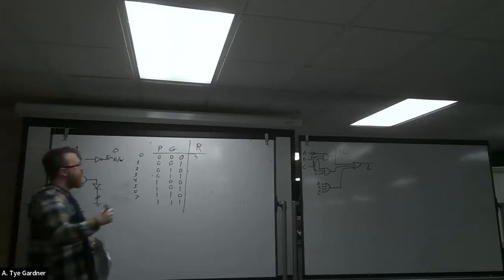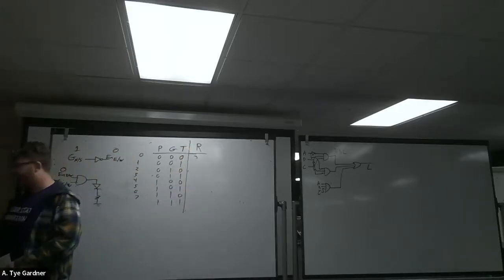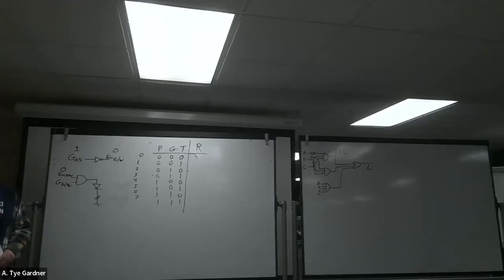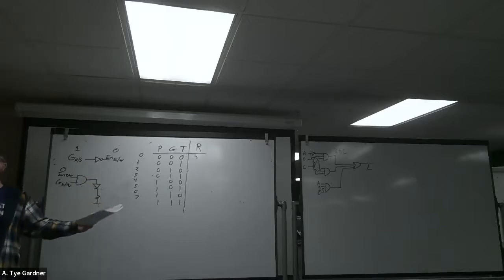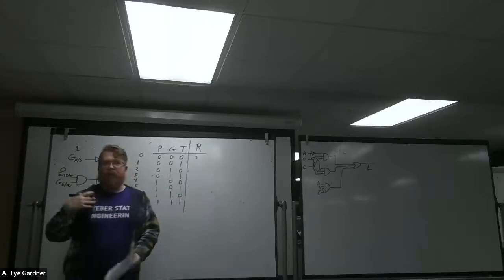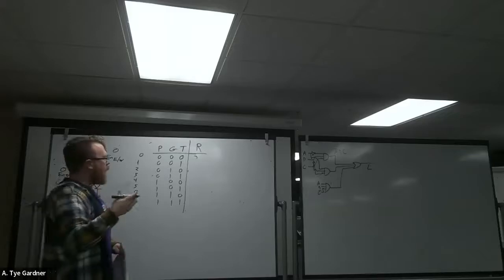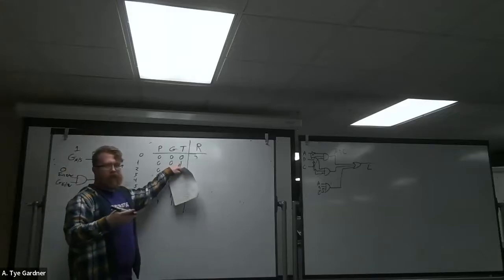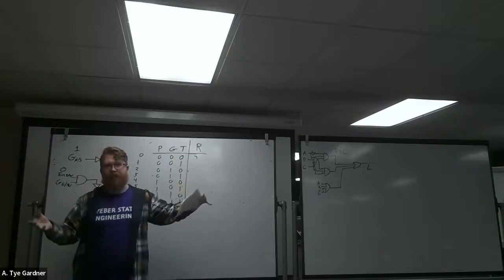And my other one is a timer. The timer says, I need Harrison to stay green for the majority of the time, right? Because that's the majority of the traffic. So don't send the request unless I've been green for a long enough period of time. So green timer is basically, for me, going to be an active low signal. The timer is running if I have a 1, and if the timer is done, it drops to 0. That's going to be my definition of what timer is doing.